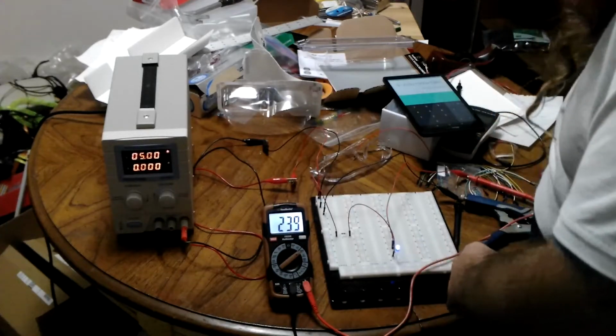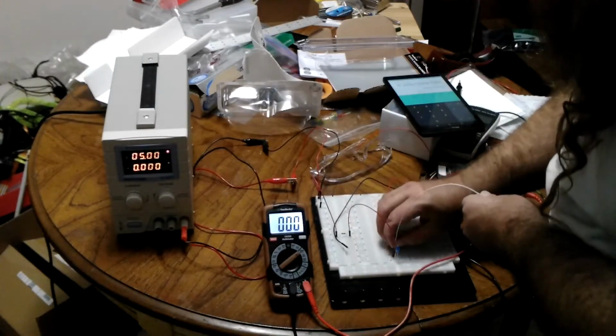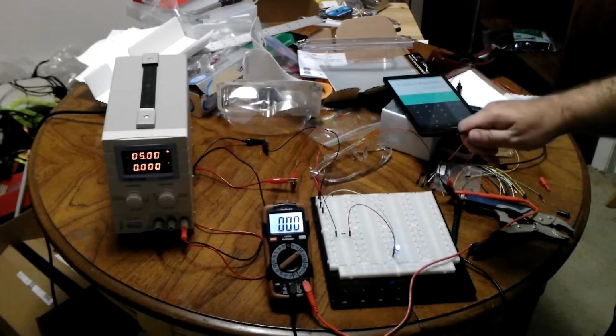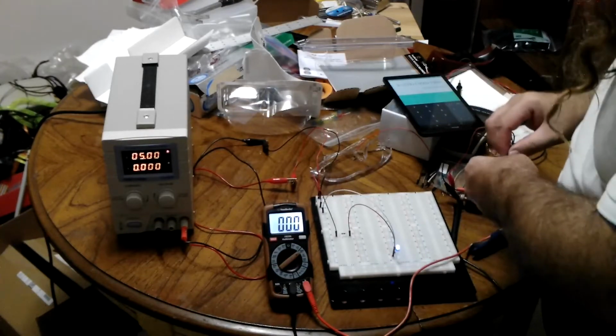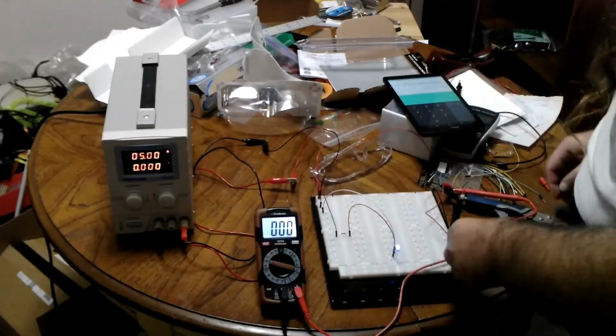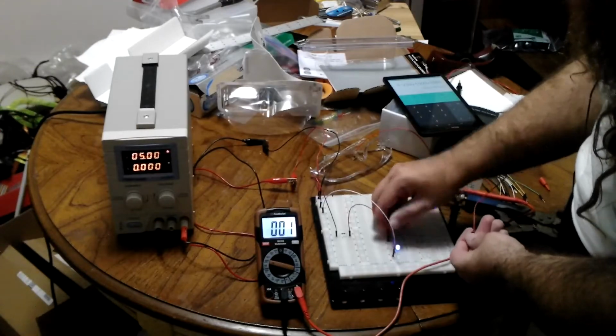Now we have to measure the voltage. So let me put the circuit back to make it independent again. So now it will light up on its own. And the current is slightly changed because there's a different amount of resistance, but it should be less than an ohm or so. So now we'll measure the voltage. We're measuring the voltage drop across the LED. So plug it in here.